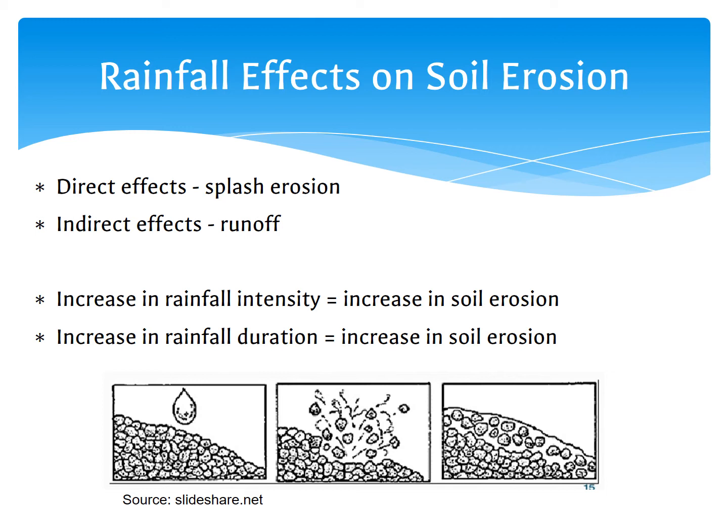This is because runoff occurs for two reasons. Firstly, if rain intensity is higher than infiltration, runoff is generated. This runoff is known as infiltration excess runoff. This runoff would not occur if the rainfall was less intense, while runoff also occurs if the soil is already fully saturated. Runoff which results from this situation is known as saturation excess runoff.